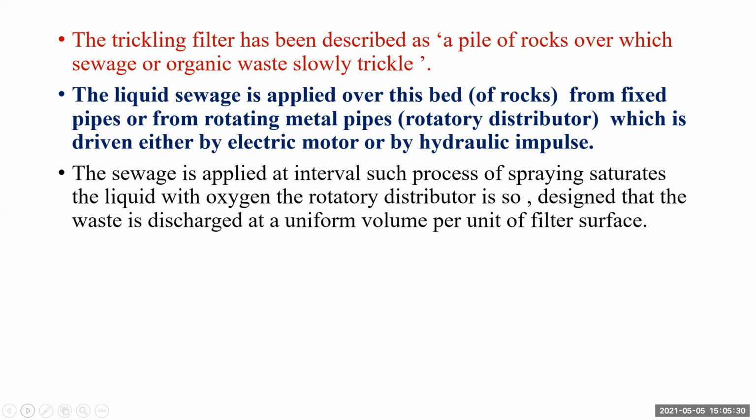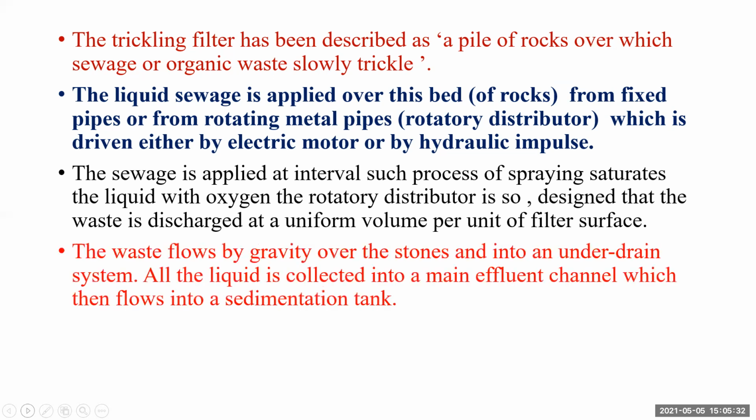of filter surface area. The waste, by the action of gravity, flows over the bed of rocks or stones and gets collected into the under drainage system. All the liquid that is collected into the main effluent channel then flows into the sedimentation tank.